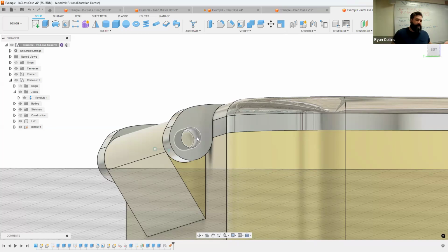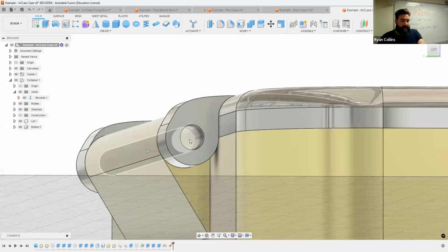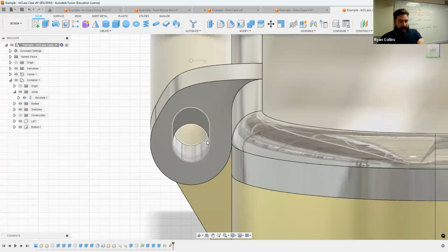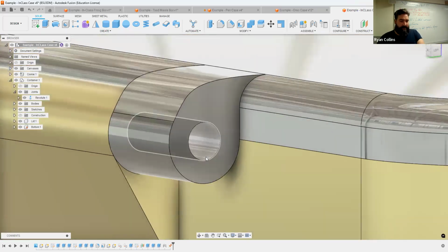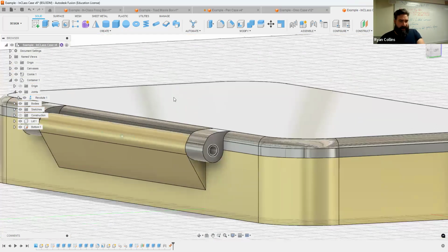But if you don't have that option, we can print something up. Now, realistically, if you are planning on printing a pin, you should definitely enlarge the size of this, because a that small a diameter printed object will be very, very delicate. You should definitely beef that up to at least 3, realistically at least 4 millimeters, if not 5. Or at that point, just use a threaded rod or something.